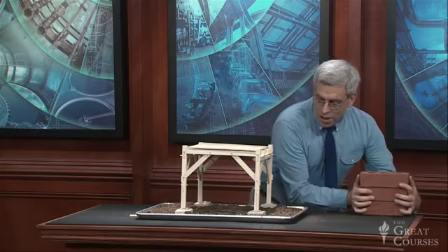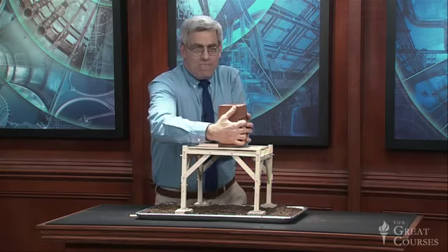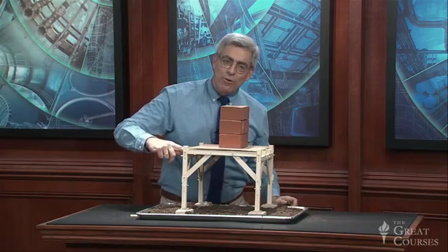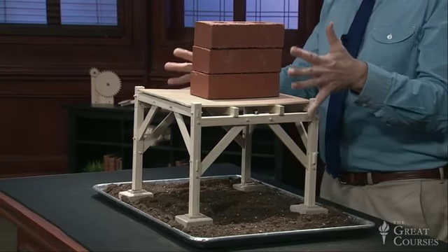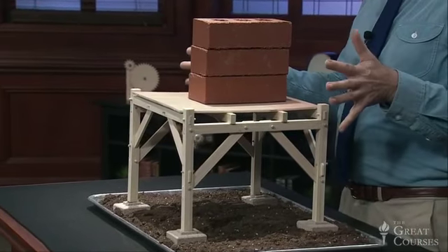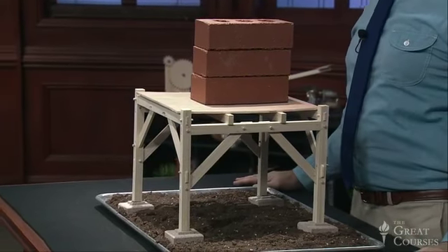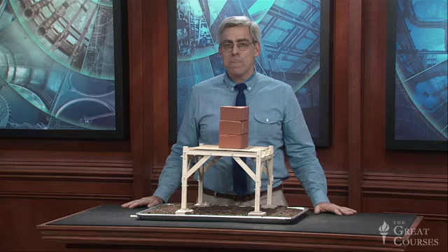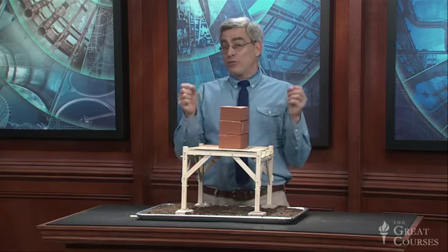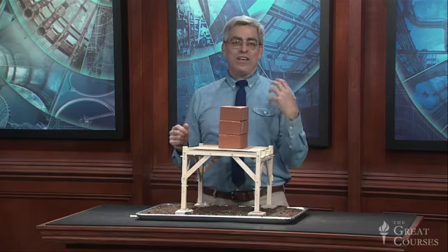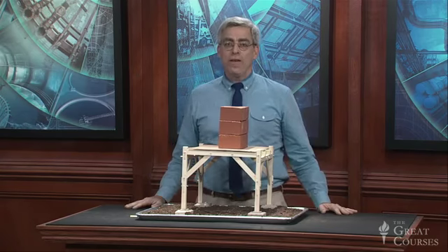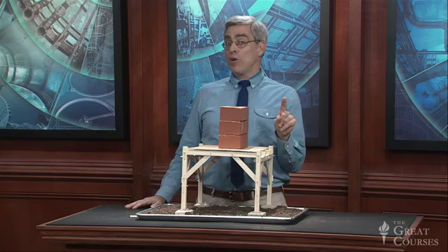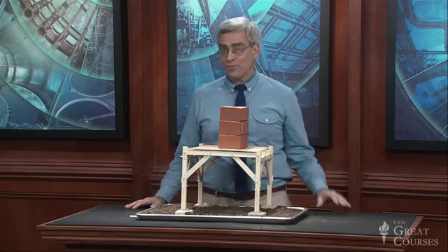We can now apply substantial gravity load and lateral loads simultaneously, and none of the previous instability that we saw in this frame is present, despite the fact that we have a substantial amount of loading on the structure. This demonstration dramatically illustrates the inherent rigidity of the triangle as a structural form. We'll see this concept again when we talk about trusses next lecture.